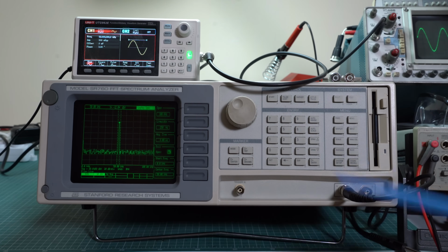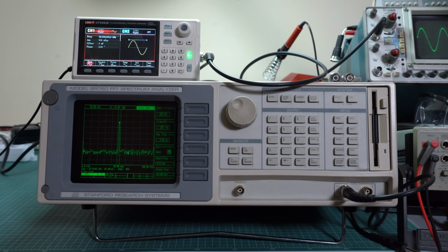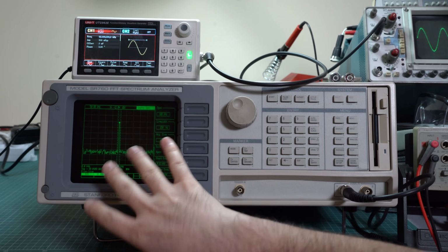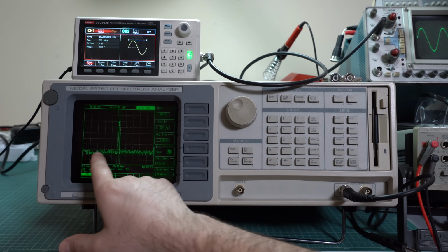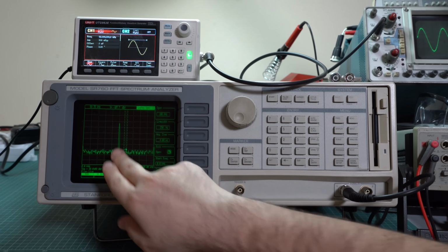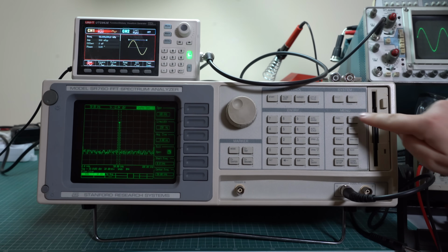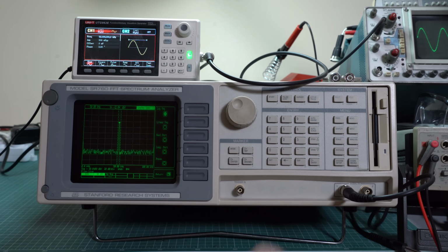Currently it has a logarithmic y-axis and a linear x-axis. So first of all, let's play with the y-axis and make it linear to see what a difference it makes in the way this signal looks. Notice the noise floor here, which is clearly visible, and also our useful signal, which is also visible here. We have a peak. Let's see how it changes when we change the axis to a linear one. To do this, we have to go to the measure menu, select display, and then linear magnitude. And as you can see, the noise floor is gone. So did we magically remove all the noise? Well, not really.